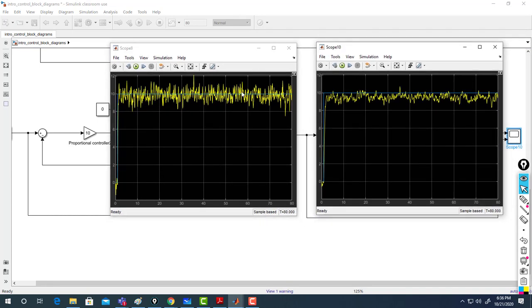The noise is amplified. That's right. I'm closer to my steady state, and my system is faster. But I achieved that at the cost of amplifying my noise, and also saturating my actuator. Good. So here there is a trade-off. You as a designer need to make a trade-off. If you have a lot of sensor noise, then think about noise amplification.